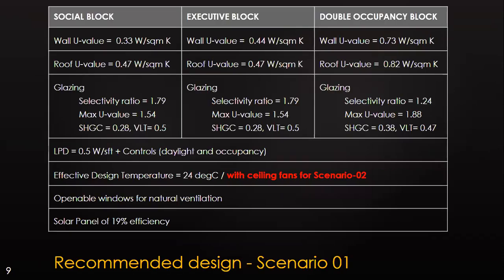Now here is a summary, but then I'll show you a little bit of the process as well. The client really wanted to know what amount of insulation is going to be used in the project. Because in terms of architecture, everything was taken care of, the orientation, it had deep overhangs, and we need to spec a glass for this project. So basic climate responsive design strategies were considered in the project. And so having that in place, what's the U value of the walls? That is, what is the insulation we could add to the wall?